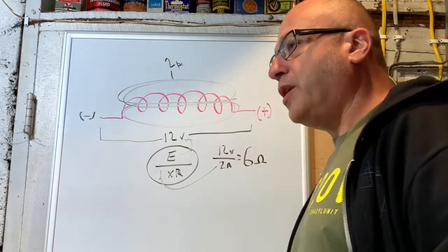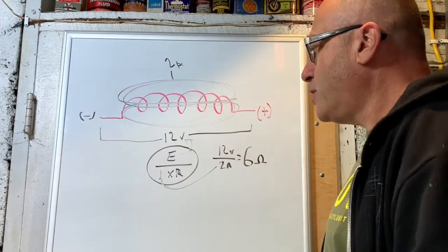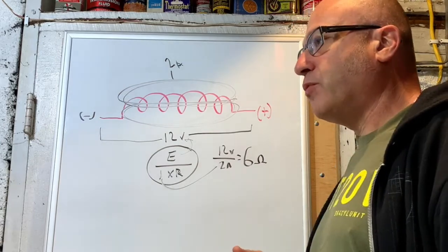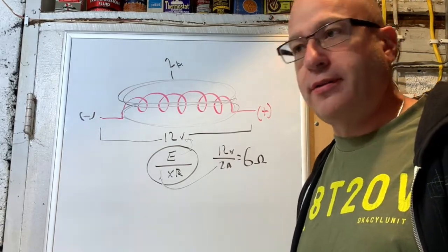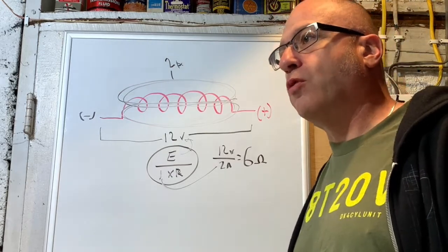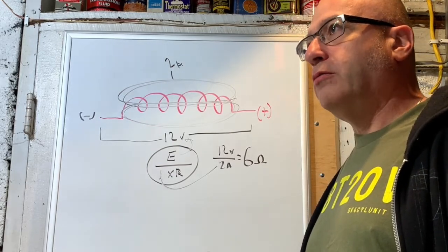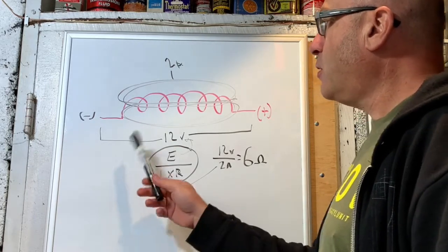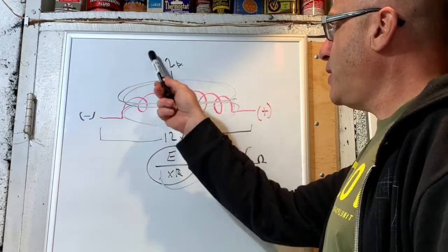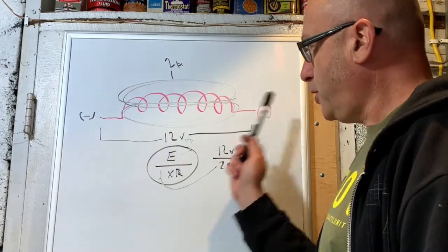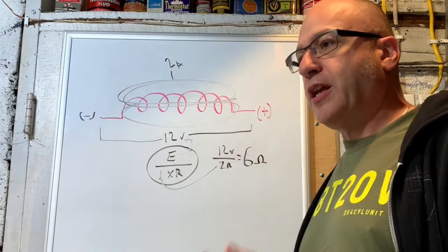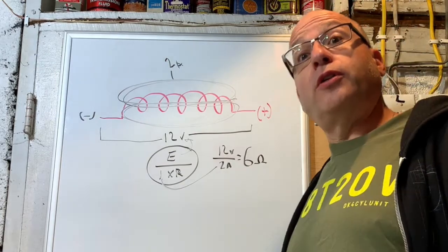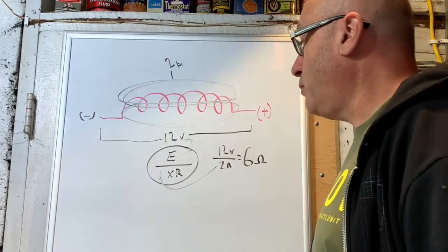Now, Ohm's Law, we know, lies sometimes, but just stick with me for this example, because we're going to damage this coil. We're going to break it, okay? And we're going to explain why broken coils don't work the way they should, okay? So the computer that's controlling this expects to see 2 amps of current pull to generate the proper type of magnetic field to do something. Move a fuel injector open, that oil control solenoid works that same way as well.